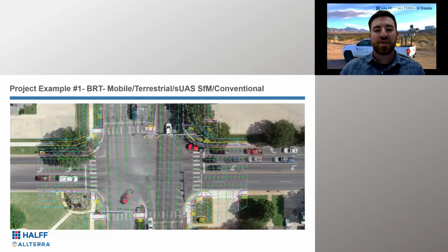And here's a top down where you're seeing the drone imagery that was utilized for different things. One of the uses for the drone imagery, because it's such high resolution, we were able to utilize it to pull out utility markings. And so using that in collaboration with conventional utility survey work and all the information you get from the utility providers, we were able to use the drone imagery to further extract our utility information.